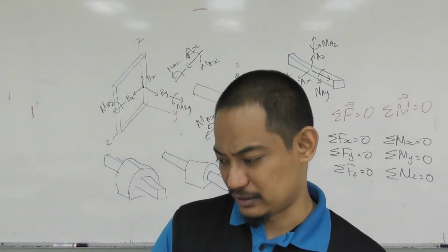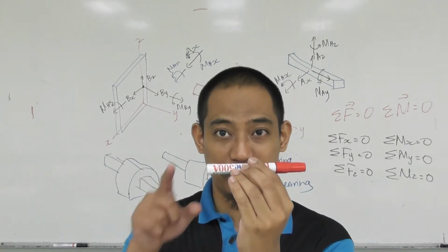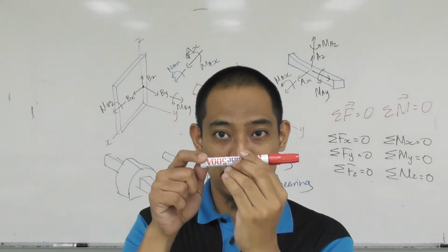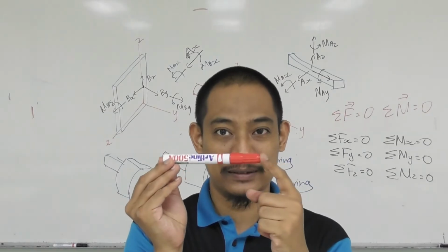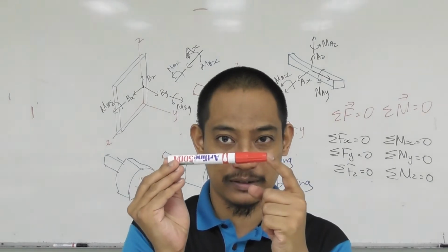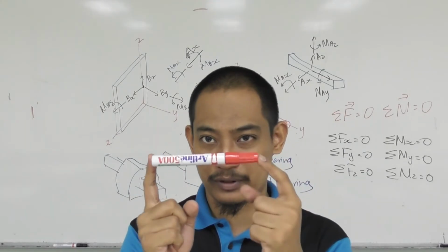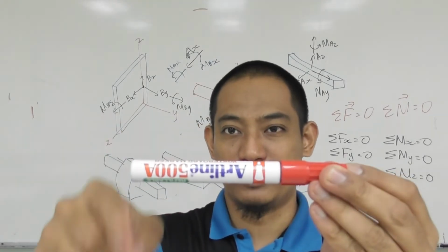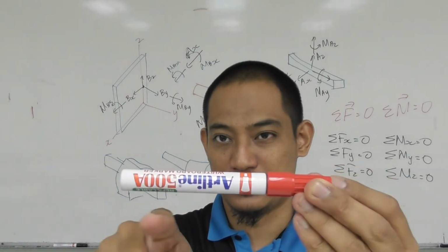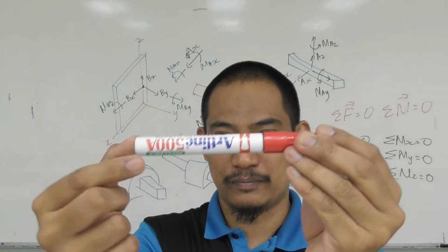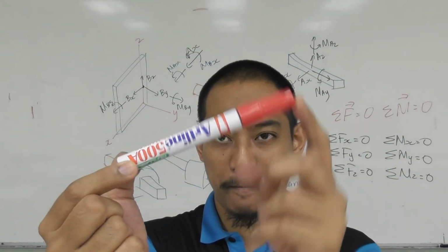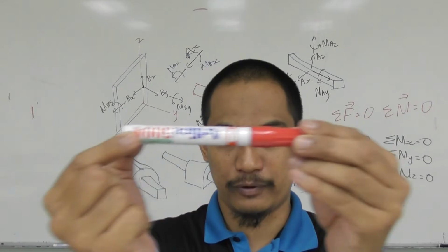Another example is a 2D example, where you have a pin support here, and then a roller here, not down here but here. This pin support prevents moving up and moving horizontally, but you can rotate. You can rotate, you just cannot move up or horizontally here.